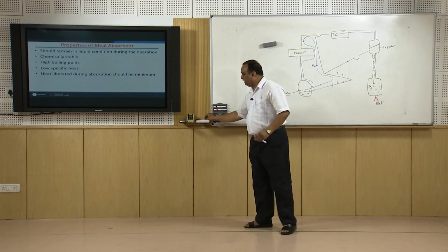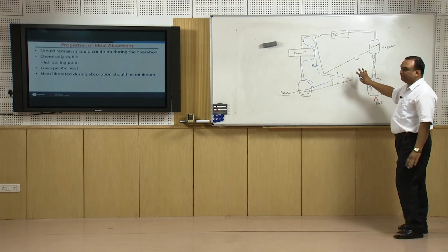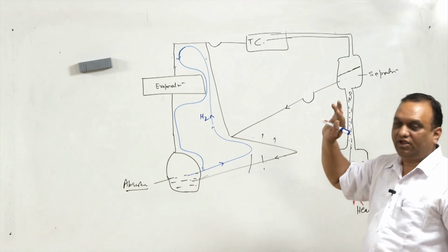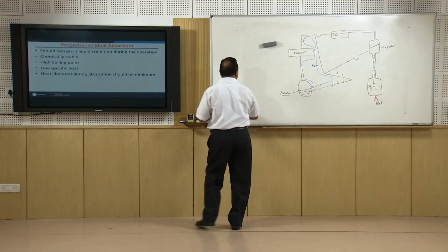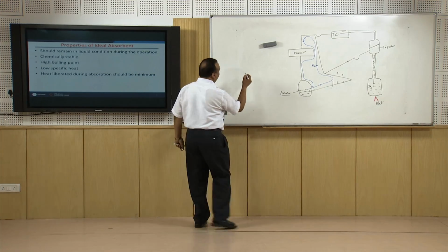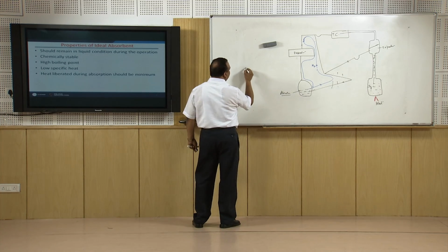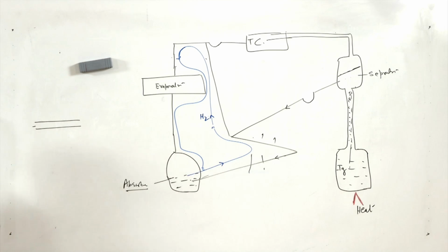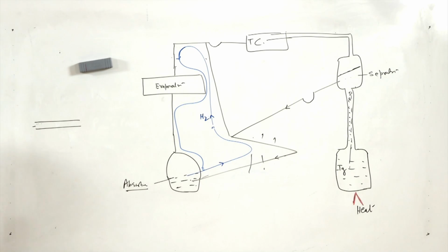It appears to be a little complicated because there is no moving part, there are no valves, only vapor locks are there. Now, I will give you another example of how these vapor locks are effective. Suppose in a horizontal pipe, it is altogether a different problem related with fluid mechanics. Suppose in a pipe, I want to ensure that during the flow the pipe is fully flooded. I mean, there is no vapor or air in the pipe irrespective of the flow rate.